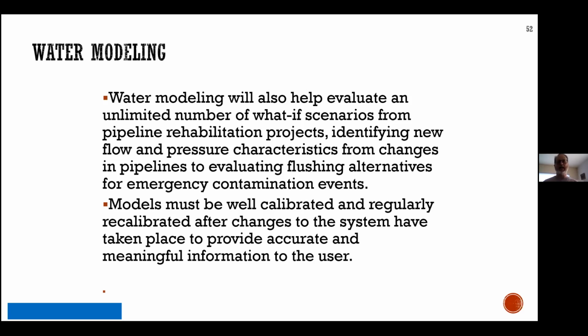And how we calibrate them is typically operators in the field going out with pressure gauges and sometimes pitot gauges to actually flow the system and see, okay, is it performing like it's supposed to? Because if it isn't and your customers start complaining, it's a little late.